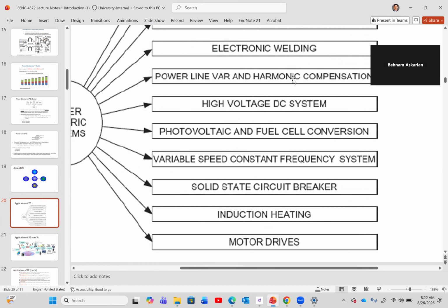As you know, with synchronous motors, the speed of the motor is relevant to what? To the input frequency, okay? If you remember, it's 120 F over P that gives us the revolutions per minute, or N. So the higher the frequency, the higher the speed. P, the number of poles of the motor, you can't change while the motor is running. Obviously, it's the characteristic of the motor. The only thing that we can change is the frequency to change the RPM.